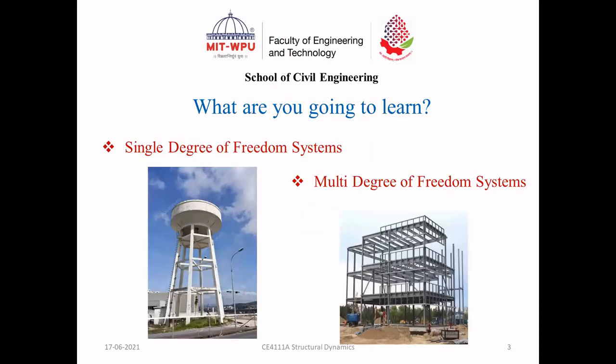In this course, therefore, we are going to answer a few questions like how does a single degree of freedom system or a multi-degree of freedom system respond to a seismic excitation or earthquake excitation. If you look at the first structure on the left, that is an elevated water tank, most of its mass is concentrated at the top, whereas the stiffness is concentrated along the columns. Such structures are called lumped mass systems, and if there is only a single lumped mass, that is a single degree of freedom system.